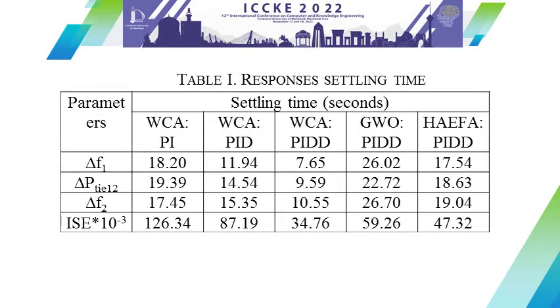So, these are the responses' settling time, numerical analysis. Here are the settling times of the responses: for PI optimized with the WCA algorithm, for PID, PIDD, PIDD based on gray wolf optimization, and PIDD based on the hybrid artificial electric field algorithm. If you see, definitely the PIDD controller with the water cycle algorithm reaches the steady state condition in quick time.